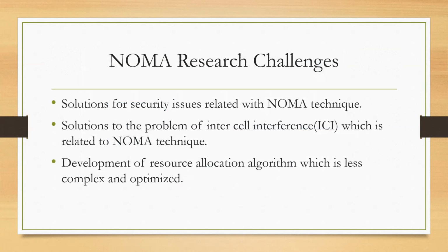Now, like every new technique, we have different challenges along with NOMA also. There is a security issue, since, as we discussed earlier in SIC, along with the original signal which is required at one's receiver, we have different users' signals also, and we decode those signals in order to get the original signal. So this can pose a security issue. A very good encoding for different signals is required in this technique.